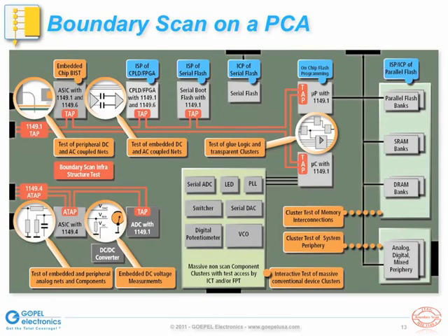On an actual printed circuit assembly, we have not only boundary scan devices, but also a variety of other types of components, including digital devices such as memories, buffers, transceivers, logic gates, and interface circuitry, as well as power supply and other analog and mixed signal circuitry. There are a number of tests that can be applied with boundary scan as illustrated on this slide.